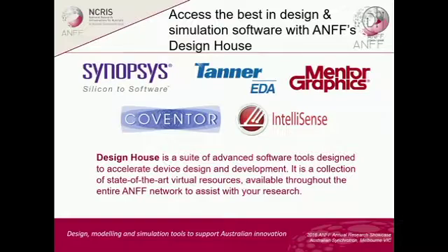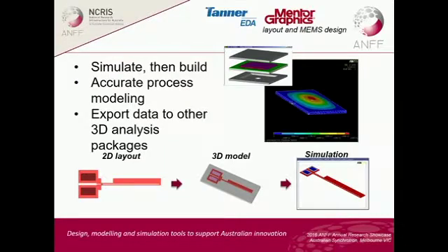And they do a software package called LEdit that allows us to do quick and simple layouts in order to develop photolithographic masks. With LEdit you can do 3D modeling and simulation, but generally what we tend to use it for is just the layout. So we'll talk through that a little bit in a minute.